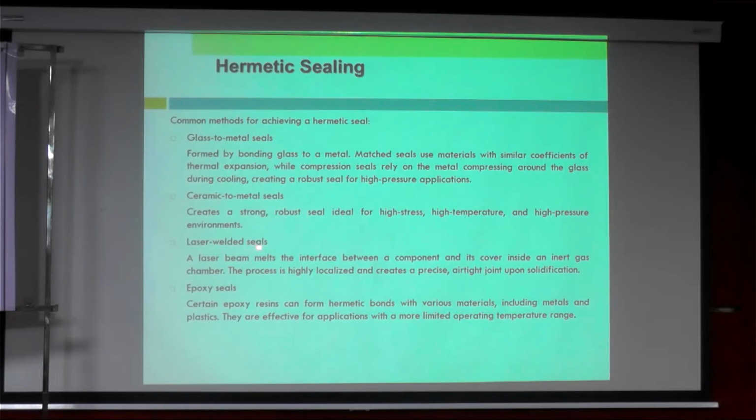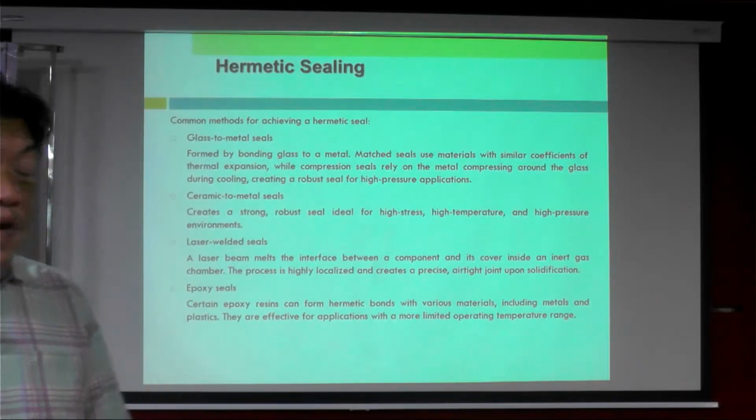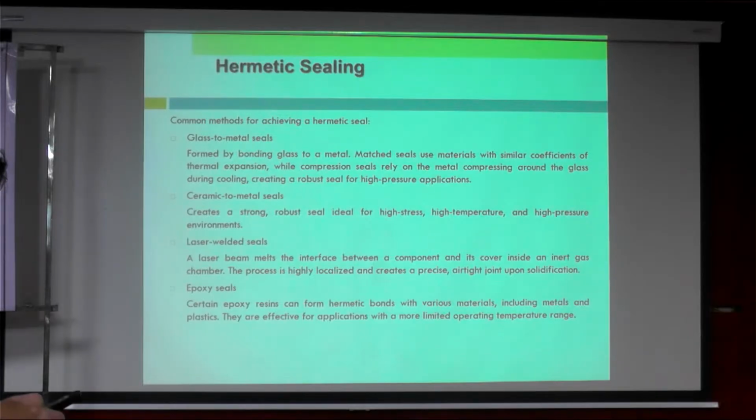Then we have laser welded seal. A laser beam melts the interface between the components and is covered inside an inert gas chamber. So the process is highly localized and creates a precise airtight joint upon solidification. So it's like you are melting in a welding, but you are using a laser to melt the material.